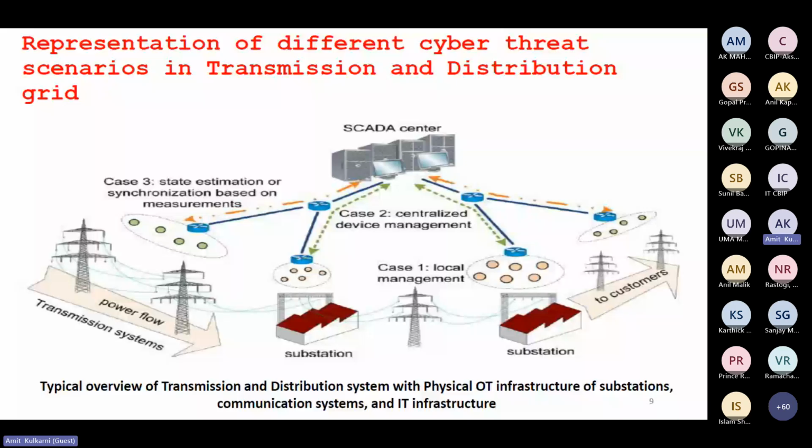The quantum of this will decide its classification and the manner in which the states of the power system will change from normal state to alert state, from alert state to extreme state, from extreme state to emergency, and from emergency, if we are unable to take any control or protective measures, the system enters the collapse state, during which we generally find the system facing blackouts. So this blackout scenario happens if the system is not acted upon timely to control the ill effects.